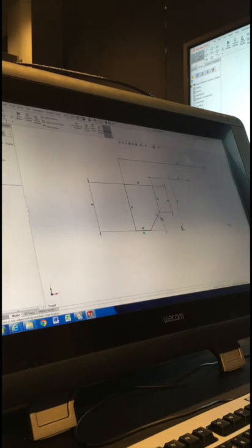Click on that first line. The vertical one. Yep. And then click on this line here. Then move your cursor to this side. Drop, and make that 6. That moves it for you. Now we'll do the same on the outside. Just click that outside line and move your cursor to that side. And 14. It moves it for you, and it'll fully define.